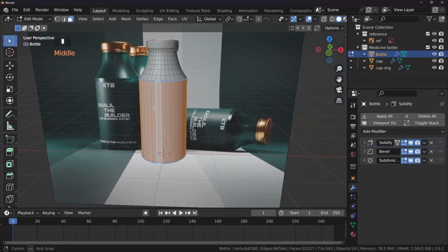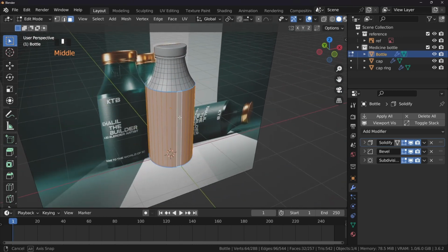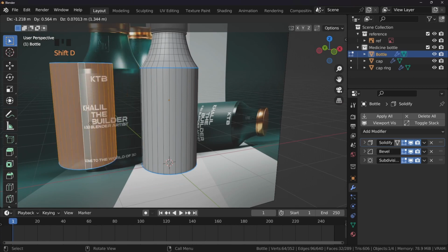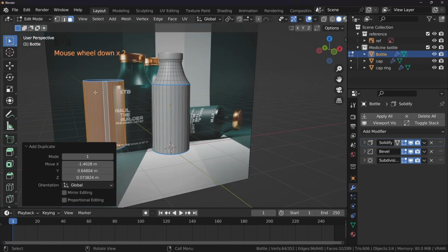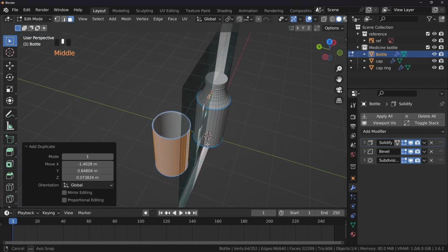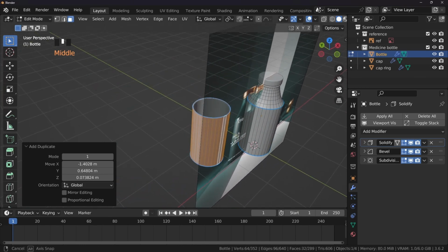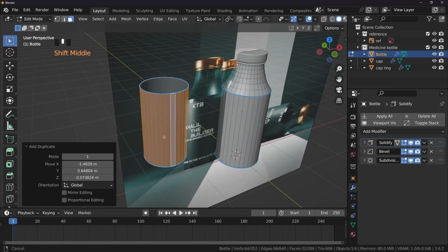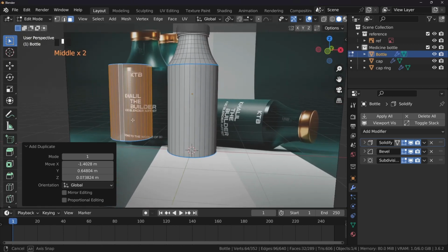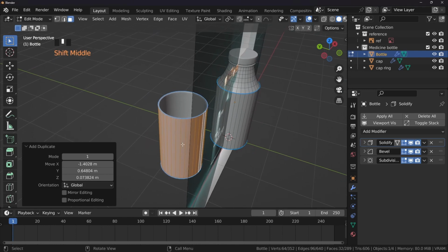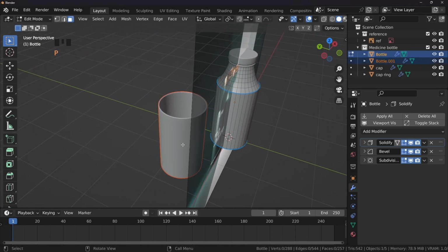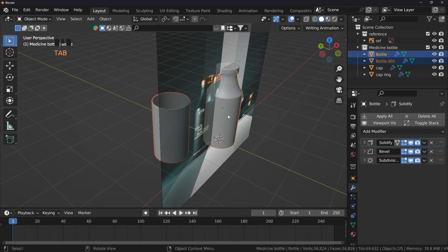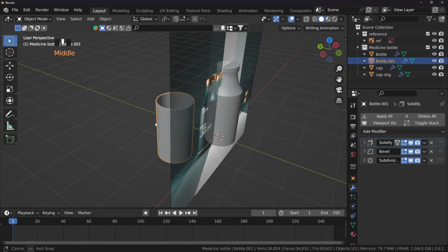Okay, now what I'm going to do, I have selected all these faces, so Shift D, and I just duplicated this one. Oh my gosh, I have grabbed this out. Can I move this back to the area there? Okay, let me press P, selection. This is now the separate object. Press Tab. This is the separate object, this is the separate object.